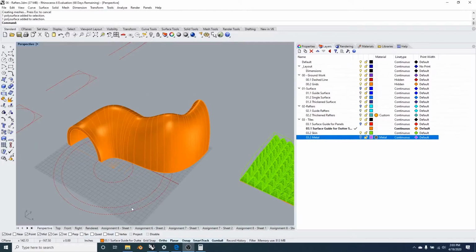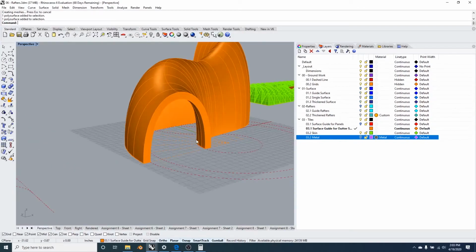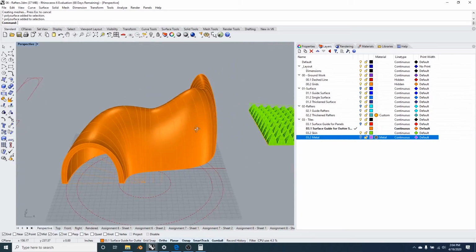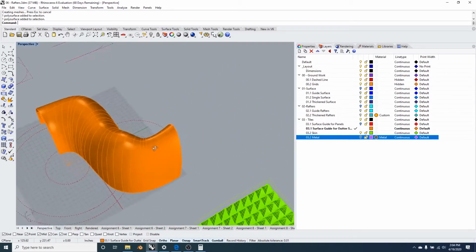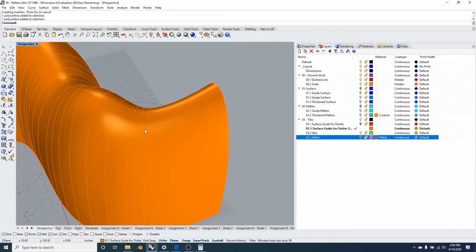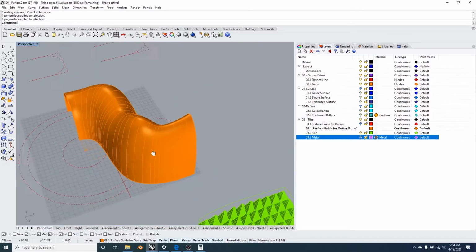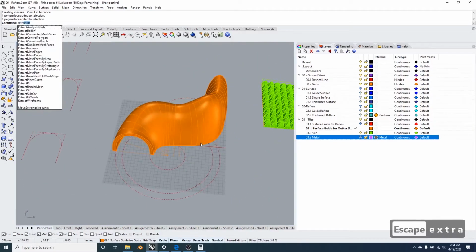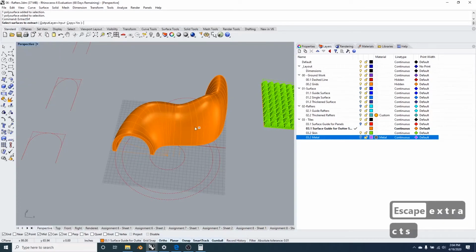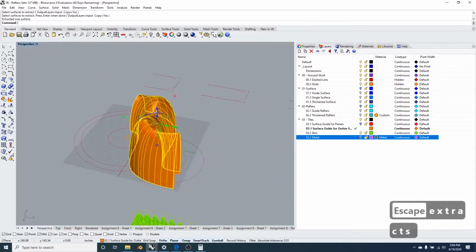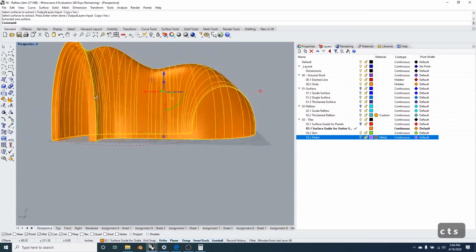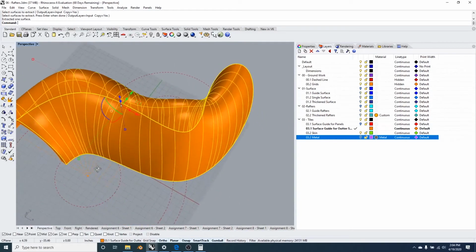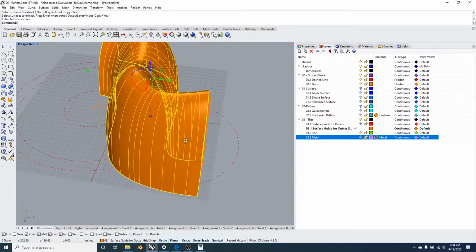Okay, so I took the time to redo the single surface, and then I offset it. Now we got a clean surface. As you can see, there are no seams in here that were preventing me before to do the flow along surface. And now I'm going to do extract surface, select my surface, and now you can see it's an entire surface that is from beginning to end, which is what we want.